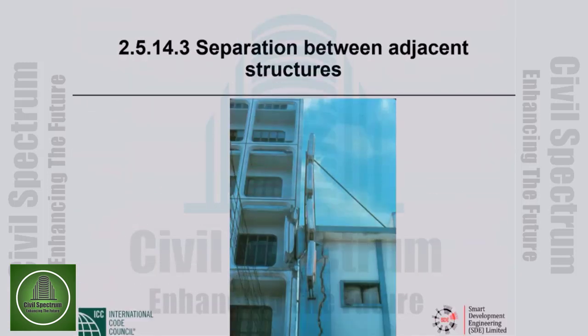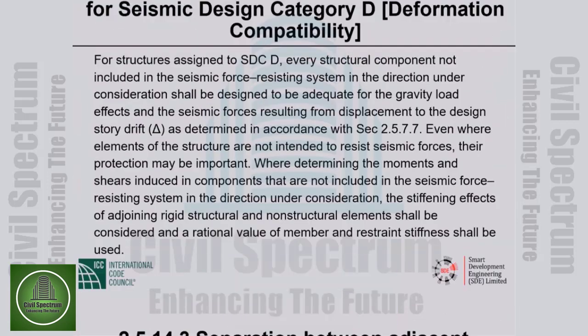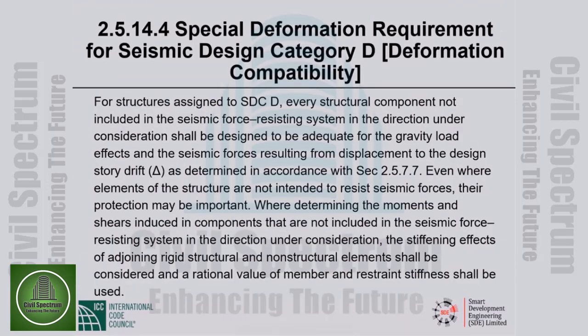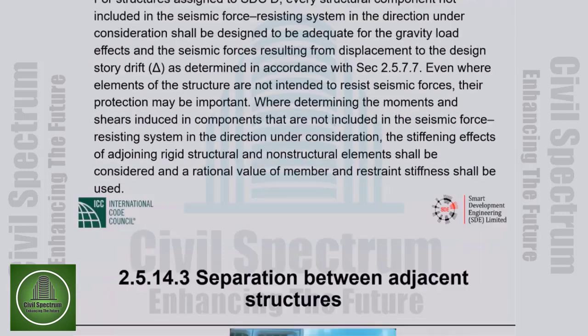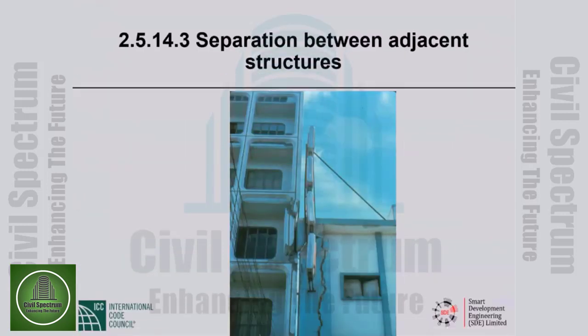I thought I put in a picture, okay, in the wrong place. This picture should be before the preceding slide. So this 30% reduction in separation distance is for when the floors are aligned together. I wanted to show you this old picture. I think I took it in Mexico, 1985 is my recollection.